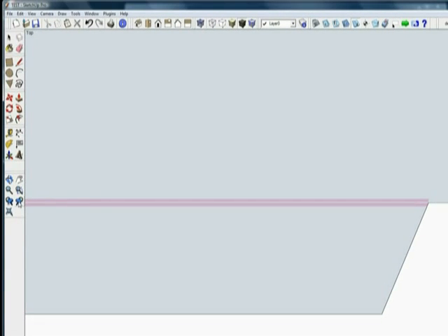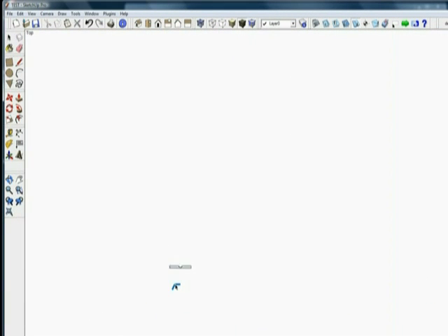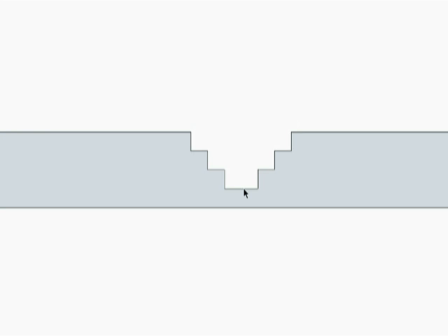Now what we've done, and I guess the easiest way to show you, zoom extents, and I can come in over here and show you, this would be a side profile of what we've done. I'm using a 1/8 inch bit, that's what I'm expecting, and this is representing the cross section of a 1/4 inch piece of fan fold foam.